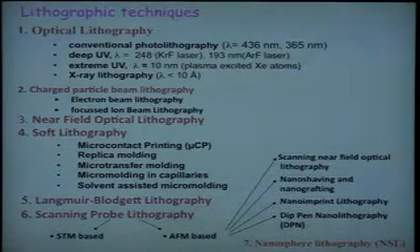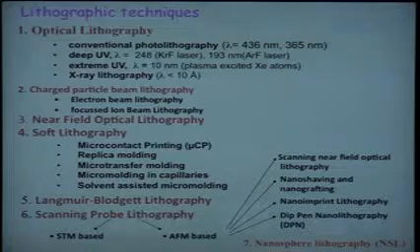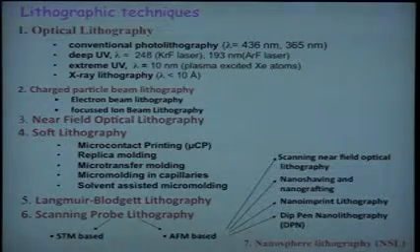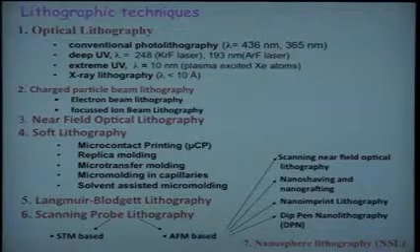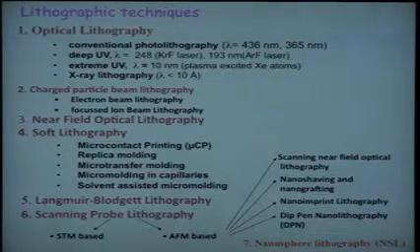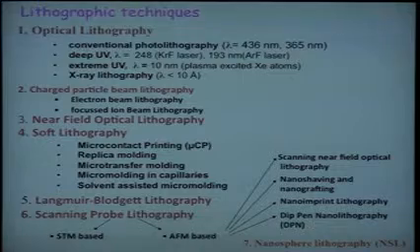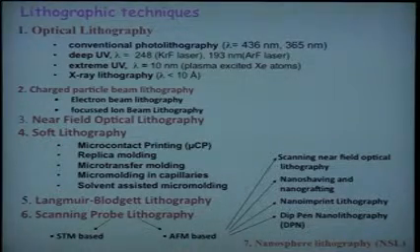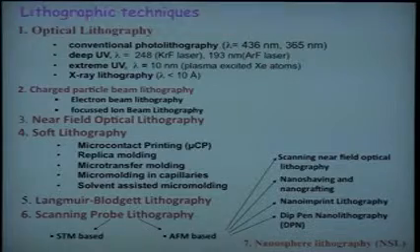Then there is yet another class of optical lithography method which does not use light in the common sense, which is all far field, but light in the near field, right? So when you have a light source, a scatterer for example, if you get pretty close to it, if you're standing within a few nanometers from the light source or a scatterer, the way the light behaves pretty close to the surface is different from when it is propagating in free space far away from the source. We all use light standing far away from it, but if you go very, very close, light behaves in a very different way, wherein it is not restricted in terms of the diffraction limits, and that is what is being exploited when creating near field lithography.